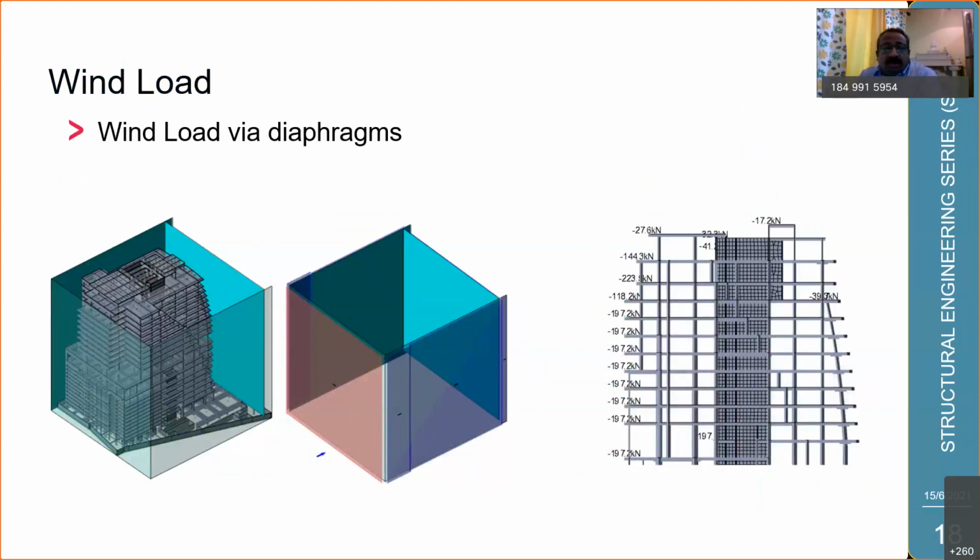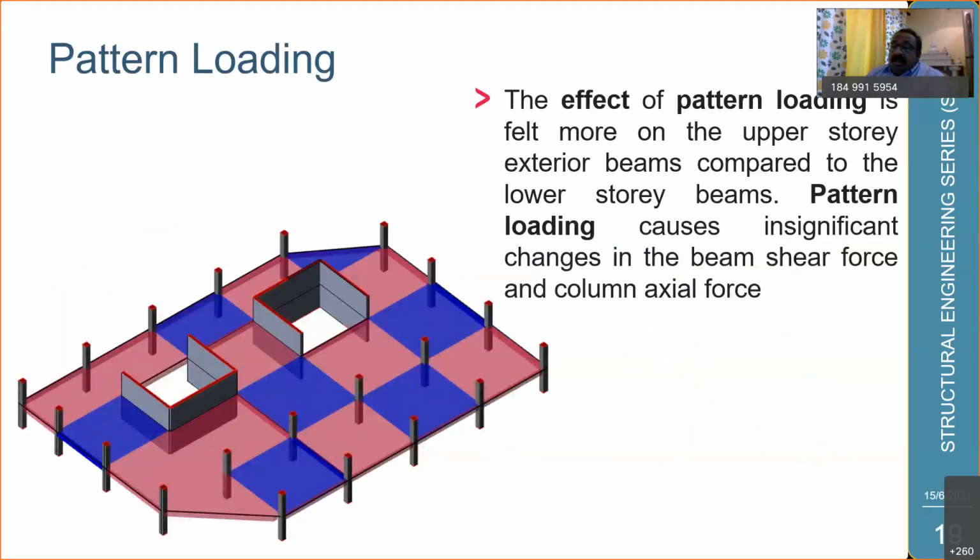For auto-wind load cases and the rigid diaphragms, loading is applied at the geometric centroid. In case of semi-rigid diaphragms, auto-wind loads are distributed in 10 nodes, so that the summation of these forces with respect to the centroid will be equivalent to the lateral and torsional wind cases. That is something possible.